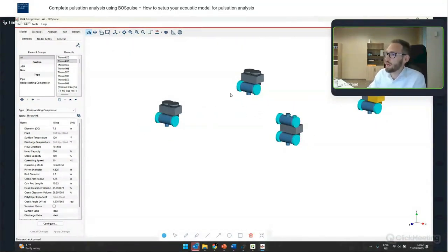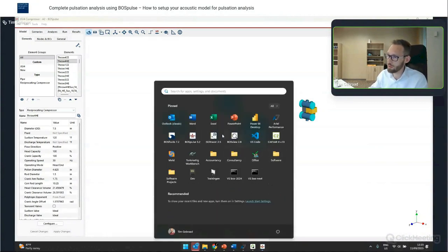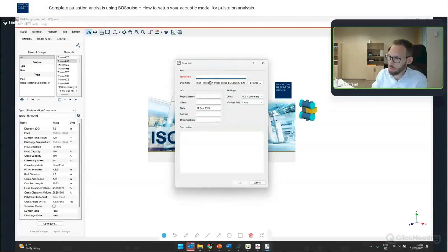And then the next thing to do is connect the first stage to the second stage. So these throws form the first stage. These ones form the second stage, and we're gonna connect them up. And in this example, we have isometrics for the interstage piping. So we're going to use our tool IsoTracer to model that interstage piping.